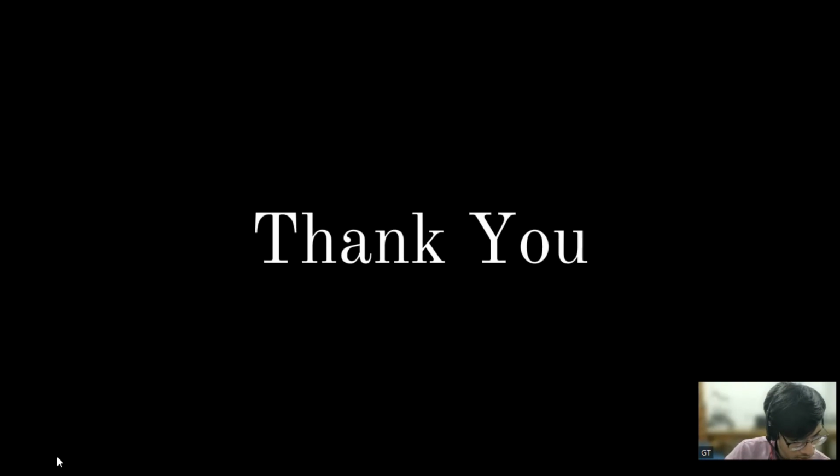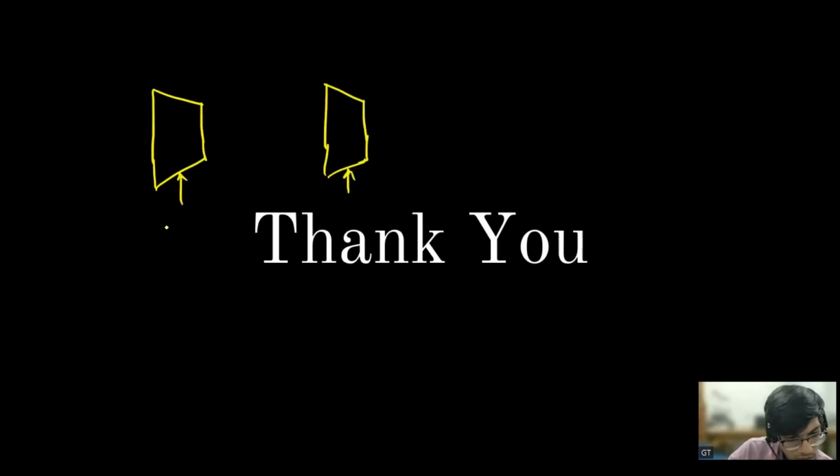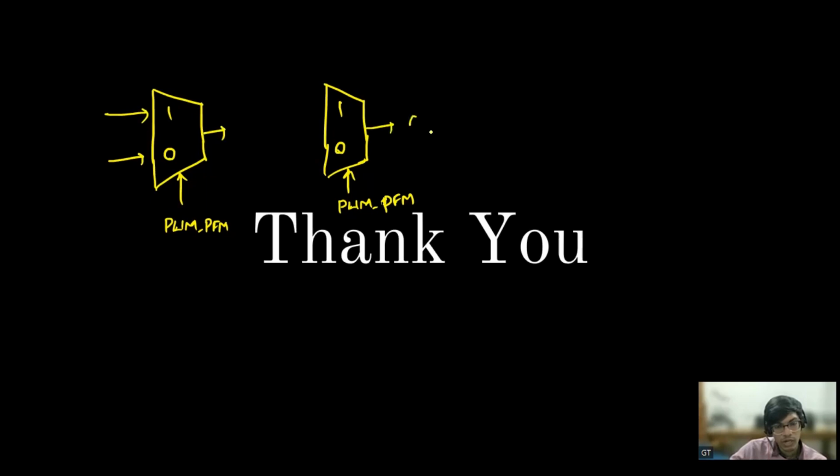Let me draw. So we are considering PWM PFM select line. It has 1, 0, and it has two muxes. One is for the high side, one is for the low side. So the outputs are QH and QL.